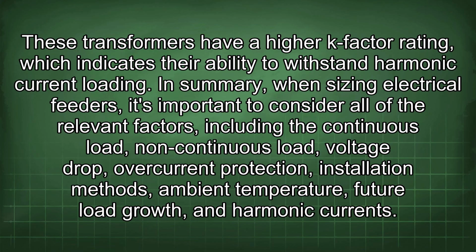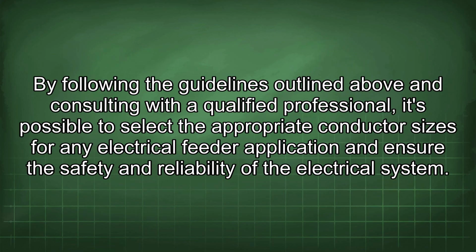In summary, when sizing electrical feeders, it's important to consider all of the relevant factors, including the continuous load, non-continuous load, voltage drop, overcurrent protection, installation methods, ambient temperature, future load growth, and harmonic currents. By following the guidelines outlined above and consulting with a qualified professional, it's possible to select the appropriate conductor sizes for any electrical feeder application and ensure the safety and reliability of the electrical system.